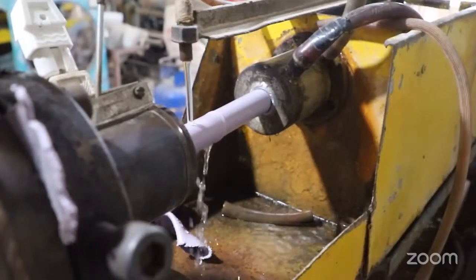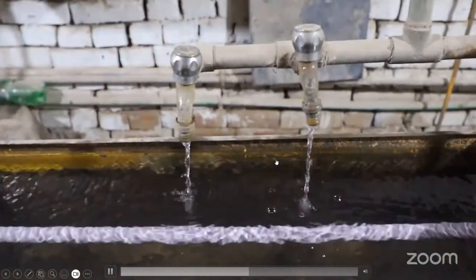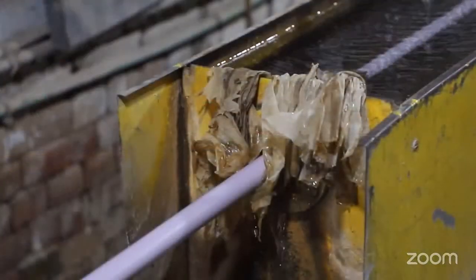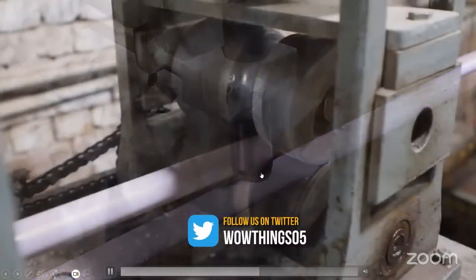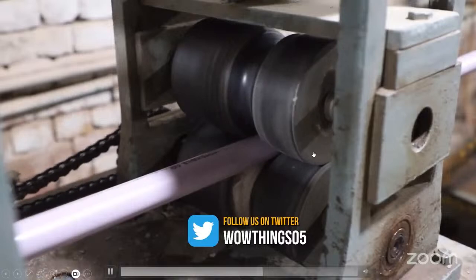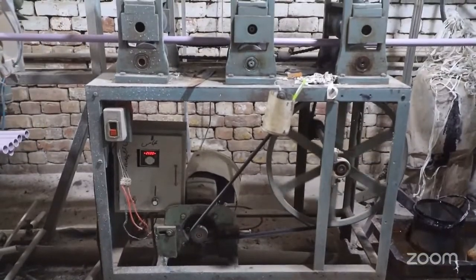See now here, friend, they are manufacturing rigid PVC pipe. See how the cooling is provided. See the printing unit, which will print the manufacturing date. There is a pulling unit, which will continuously keep the pulling effect on the pipe.